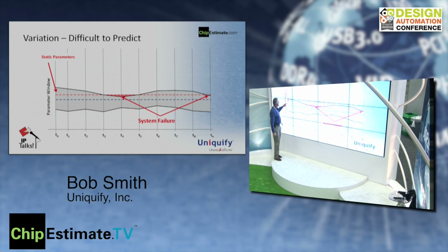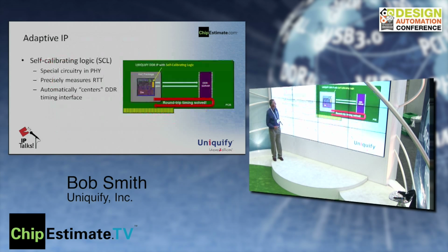So if you imagine here that after measuring a lot of different samples, we pick this as our operating point. But later we find out that I have some systems out in the field that are maybe, let's say, getting too hot for whatever reason. They're jammed in a closet somewhere. All of a sudden here, our window's shifted, and now our operating point is just right outside of it. So I'm starting to get memory misses, memory problems. Not good. Not good. I'm going to wander back over here.